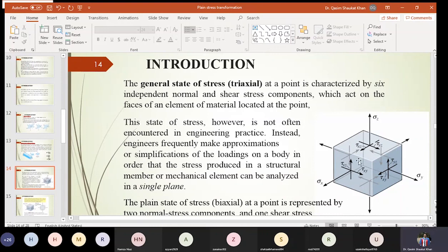Yes, sir. Okay, then you have this second shear stress that will be tau zy, originated in the z plane and oriented along the y direction. So tau zy. And why they are saying this tau yz is because it is complementary to this. So this shear stress is complementary to this shear stress. So on this face there is one normal stress sigma zz, and there are two shear stresses, tau zx and tau zy.